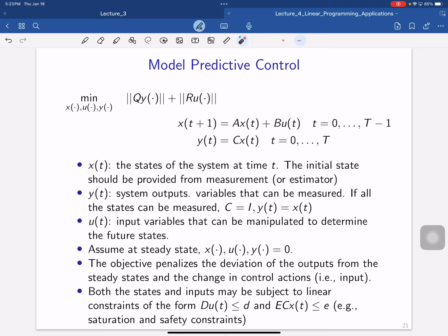And then the next state will be a function of the state at time t plus the B matrix times the manipulated variable, right? Because the way you are going to inject cooling water into the system will, of course, affect the temperature and concentration. That's what this B matrix does. There is a rich literature discussing how you get the A and B matrices. In this case, we just assume we do know a very simple linear model to approximate the ODE that is given to you, right? This class is not about getting those A and B matrices.